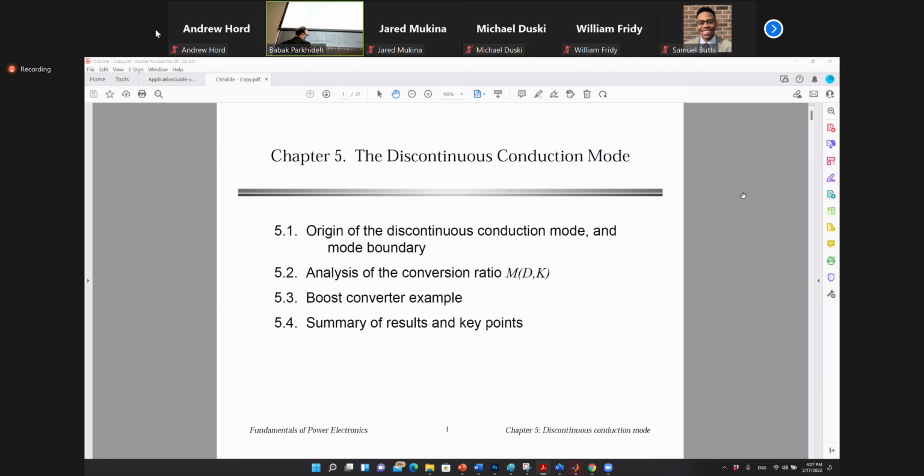And then it reaches your steady state current, right? And then whatever the circuit does, it may go up or it may go down, following the inductor current. But usually this time is so short compared to your switching period that you look at it as if it's a constant. So this is a current,